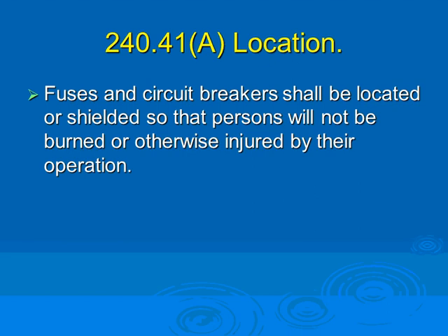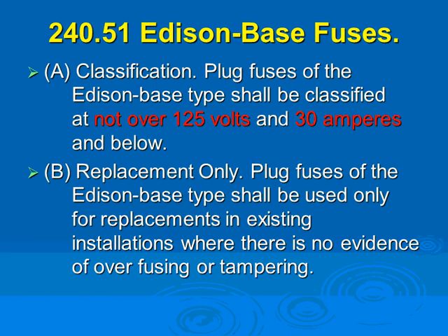Fuses and circuit breakers, when they operate, shall not be burned or otherwise injured by their operation. There are 4,000 amp circuit breakers, guys, and fused switches with handles on them, that if the circuit breaker trips while you are there, it could slam you in the head and give you a really good hit. So it has to be placed in a place where if it operates, it's not going to injure anybody. A couple of things about fuses.